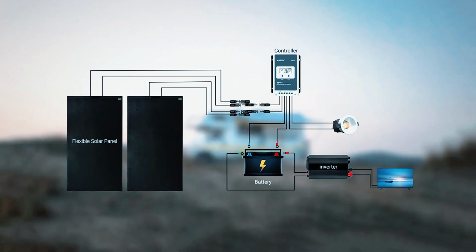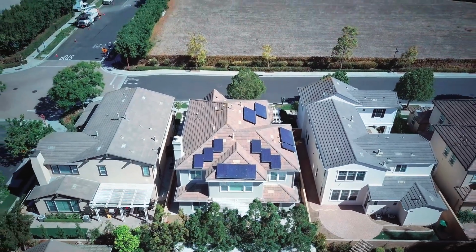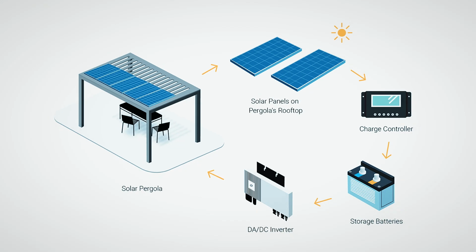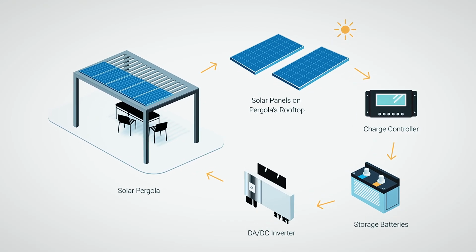When deciding whether to connect in series or parallel, it is important to be aware of the voltage and the current strength of all panels, as well as the requirements of the balance of the system, such as inverters, microinverters, solar cells, and charge controllers. This way, you can determine the best way to wire your equipment to maximize power generation without exceeding the maximum that your solar power system can handle.